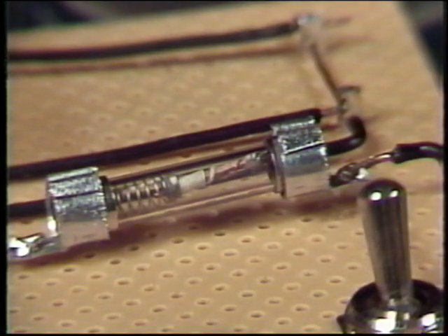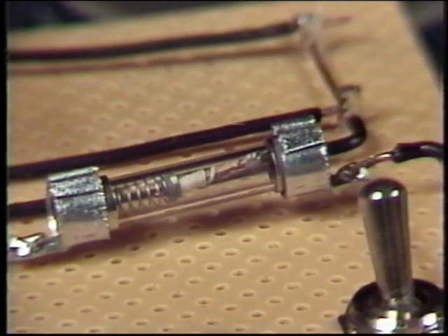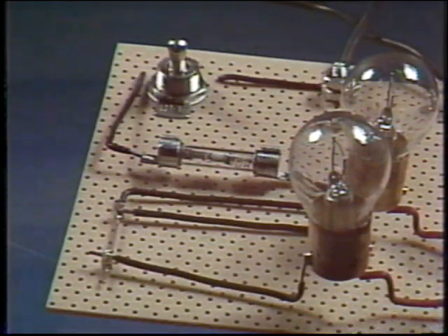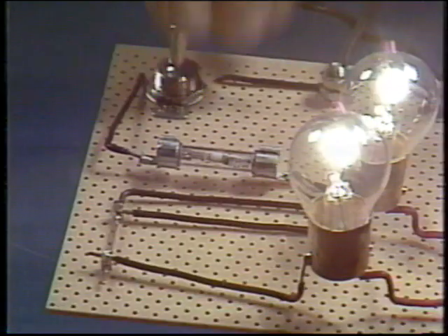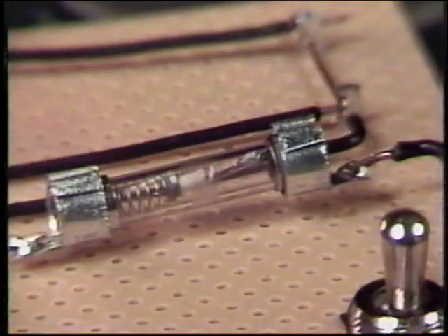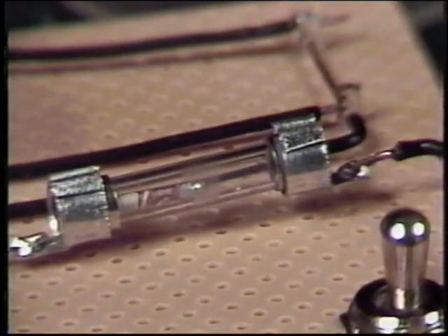The slow-blow type fuse is designed to allow momentary surges of high current, but will open the circuit if an overload is sustained for too long a period of time. The slow-blow type fuse has its fusible link connected to a spring. When sustained high current softens the link, the spring tension pulls it apart.